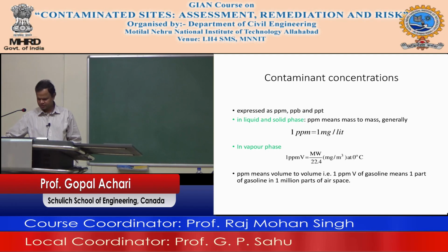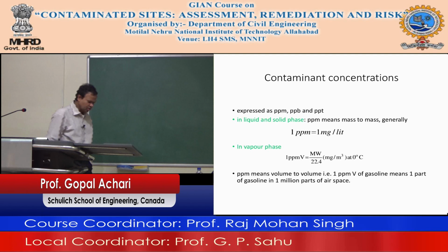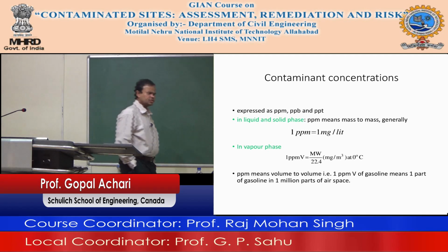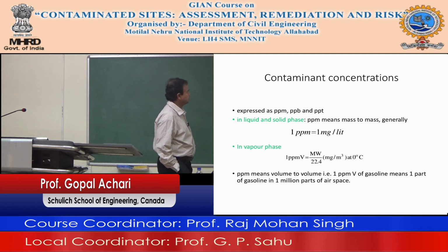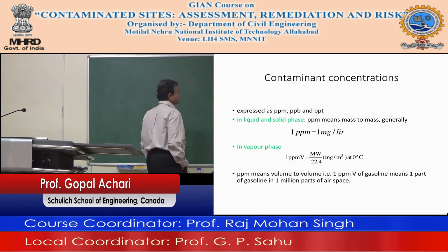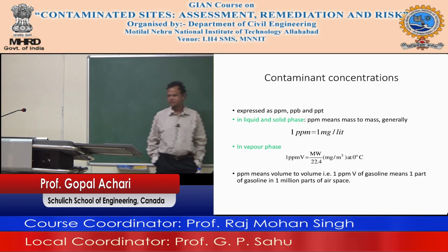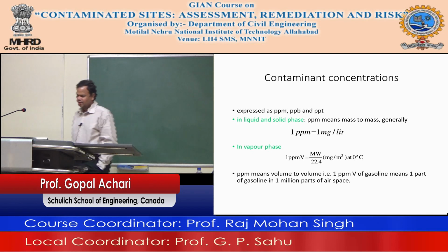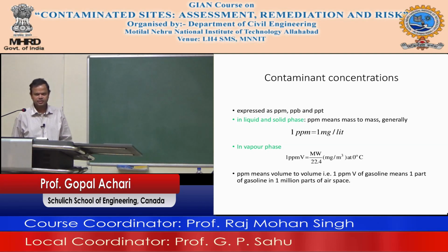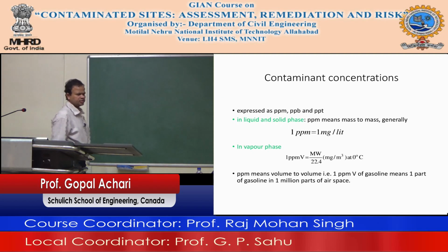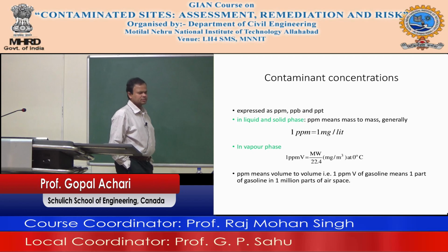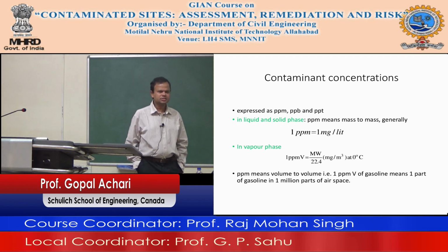Where we left off yesterday was here at design approach, selection and application. So when you're designing a remediation system, you have to consider a few things. One of them, you must have a good knowledge of the site itself. I cannot stress enough the importance of site characterization. If you work in the field, either on the client side or on the consultant side, you must make sure that enough budget is put aside for a detailed site characterization.